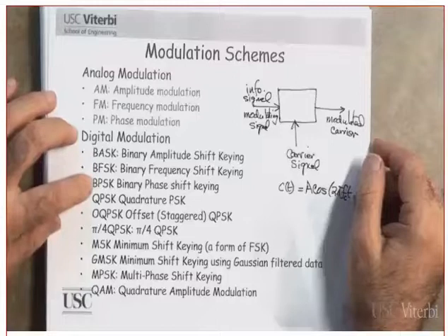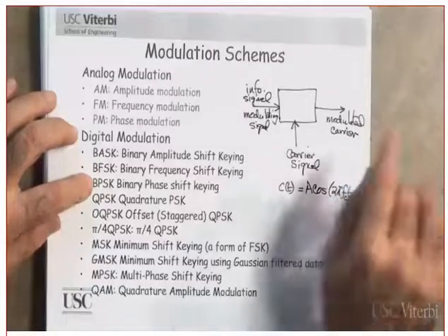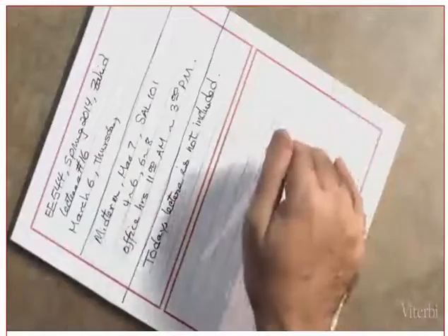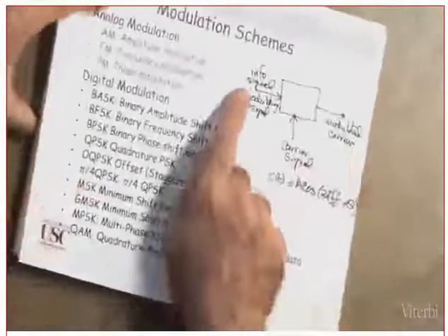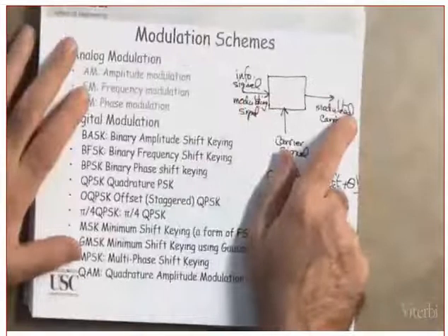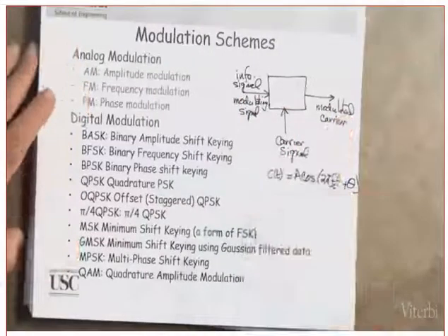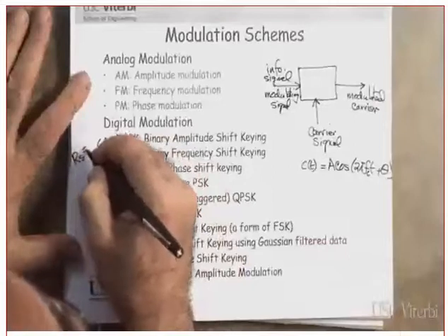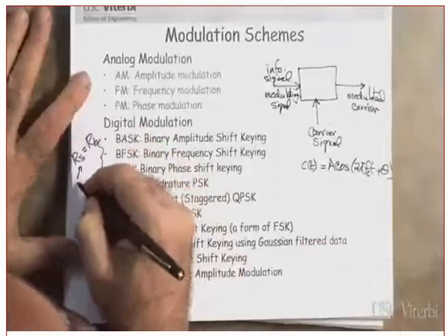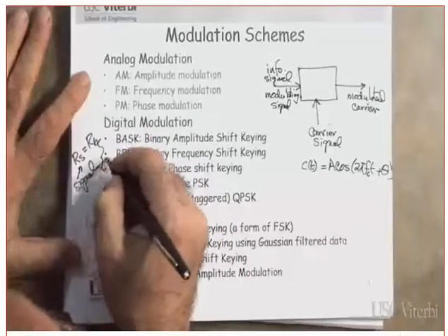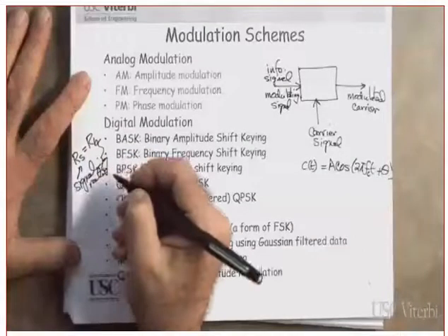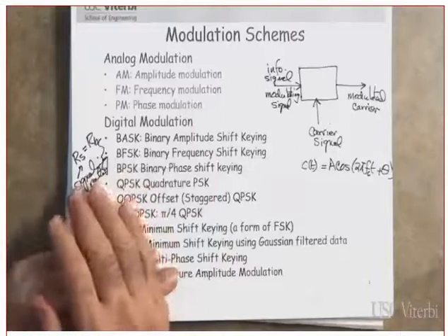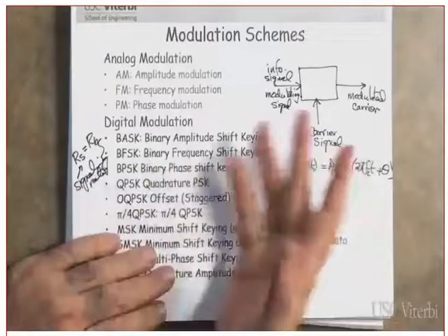Do you remember what I mean by binary? In a binary modem, every bit goes in, did we talk about this earlier or not? In this course? Okay. In a binary modem, every bit goes in, a signal goes out. Which means what? The signaling rate in a binary modem, RS, is equal to RB. This is the signaling rate. Clear so far?